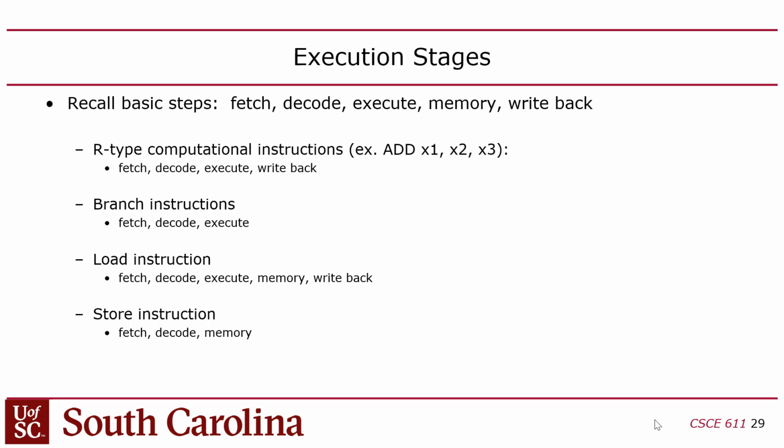Okay, so how are we going to actually fetch and execute instructions then? You might remember from 2.12 that you can design a CPU to be a single cycle CPU, meaning that each instruction is executed in its entirety within one cycle. In fact, some CPUs work that way. Microcontrollers often work that way, like an ARM Cortex M0, probably, I don't know about the later, bigger ones. Atmel processors, like the Arduino, a lot of them do execute instructions in a single cycle.